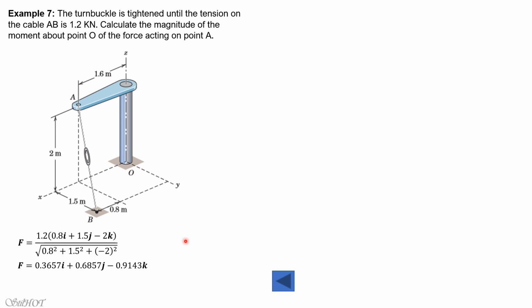So we put these components at A. So along x it's positive, along y it's positive, so to the right, and along z is negative, so going down. First, for moment about OX, so position your right thumb towards the positive x-axis, then curl your four fingers. That's the direction, that's the positive moment about OX. So it should be that way. I hope you check it with your right thumb there. So that's the positive direction of moment.